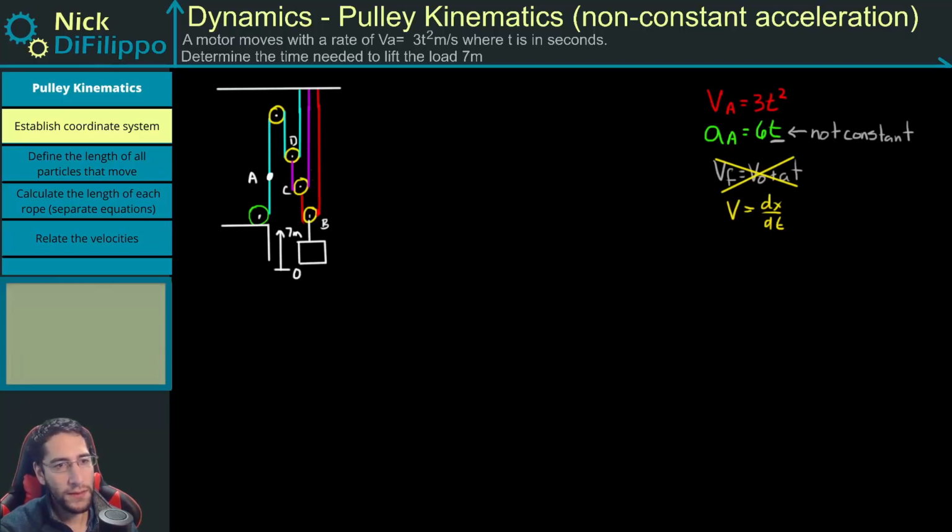So let's look at this pulley, and actually this is connected. It's not just floating there. So this is connected to a fixed point. First part of a pulley problem is always dimensioning the lengths of the moving particles and figuring out a reference point. The reference point I'm going to choose is through this top pulley. Everything right here is constant, so it's not going to change. And it seems like a good point for the reference line.